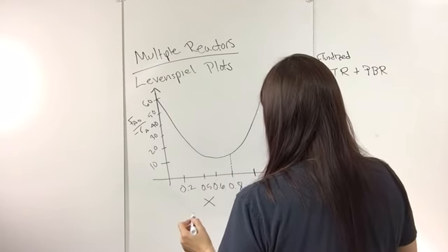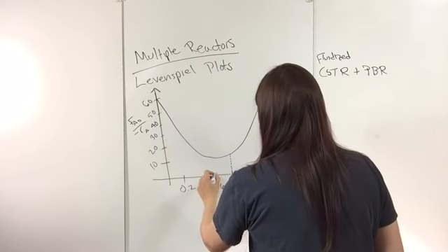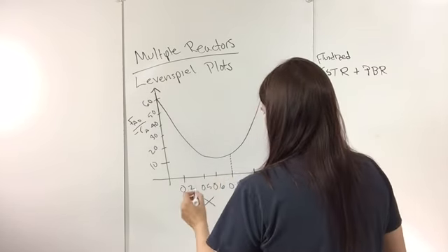So just looking at this, we know that if you remember the area of the square, so let's say you have a CSTR that's at 60%. Then this area is the size of the reactor, or in this case the catalyst weight. And then the area under the curve is the volume or the catalyst weight required for a PBR or a PFR.